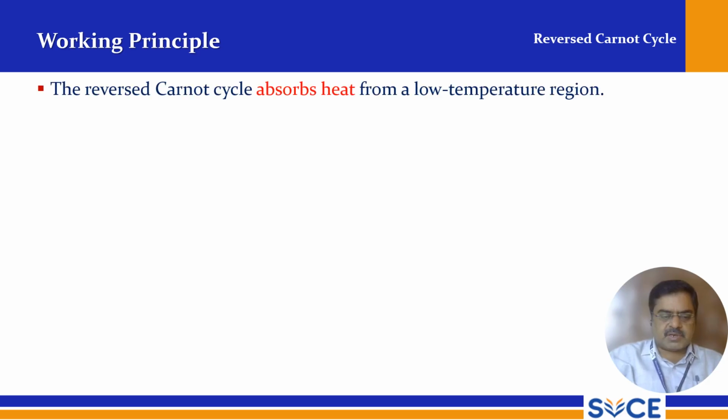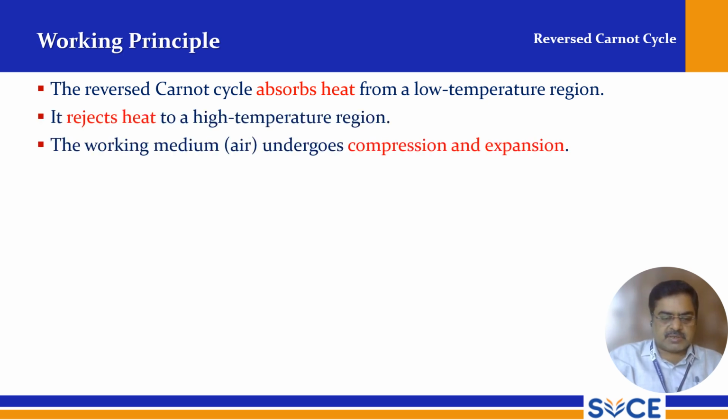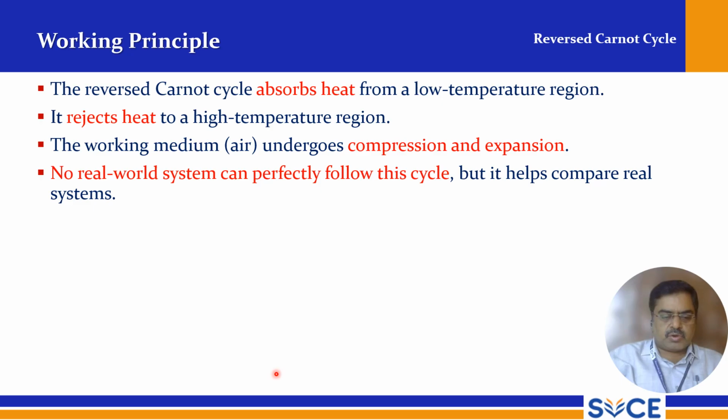The working principle: the reversed Carnot cycle absorbs heat from a low temperature region. That is why it is the reversed Carnot cycle. It absorbs heat from a low temperature region and rejects heat to a high temperature region. The working medium, air, undergoes compression as well as expansion processes. No real world system can perfectly follow this cycle, but it helps compare real systems. So we can compare our developed systems.